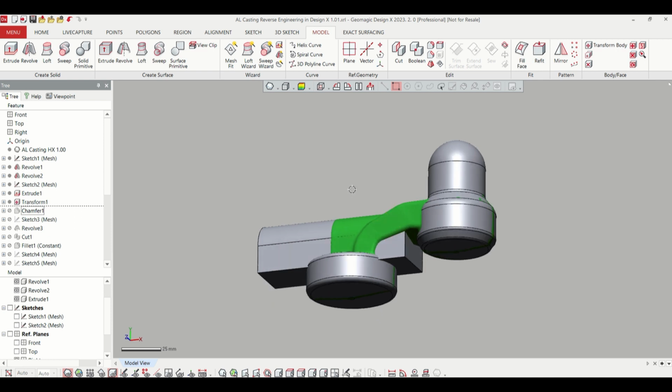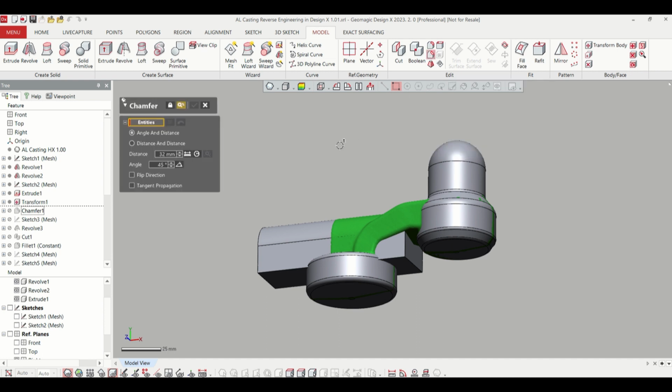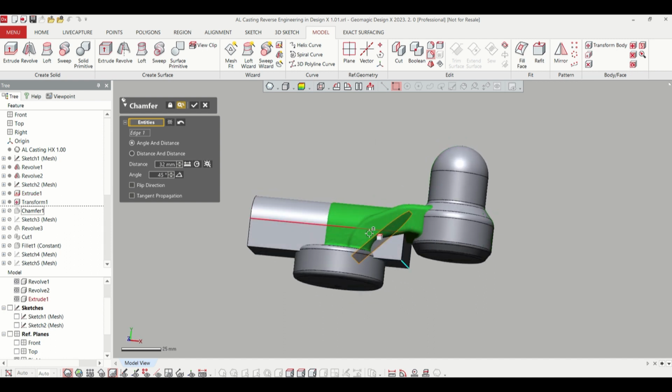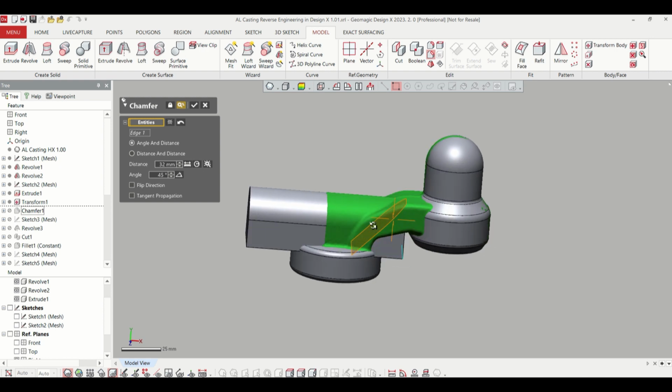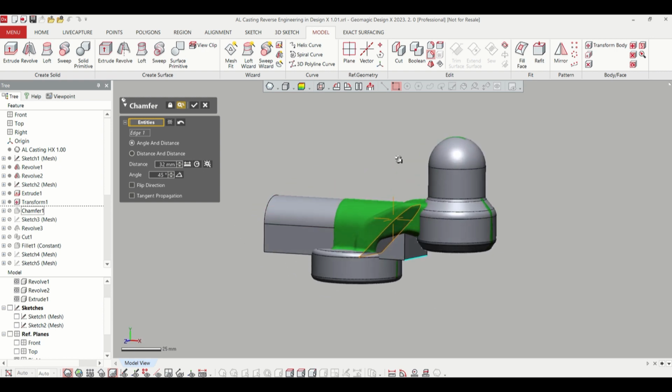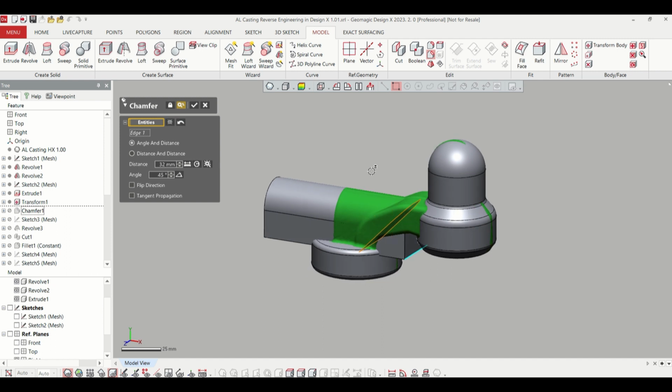Another way to do it though would just be to use the chamfer tool and pick an arbitrary dimension for removing that material. I just want to make sure that the surface that is left is going to be completely captured by the sweep that I'll create with that 4th feature.